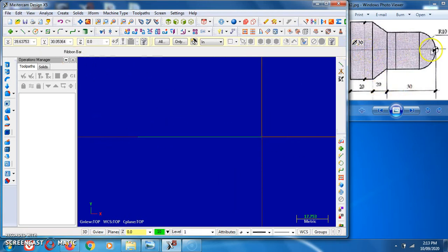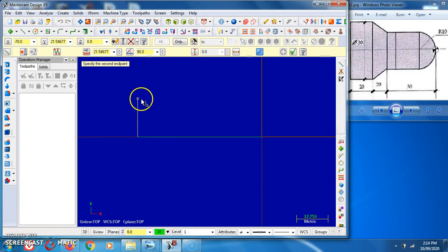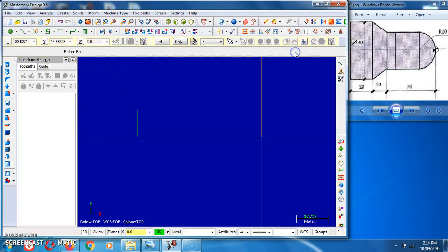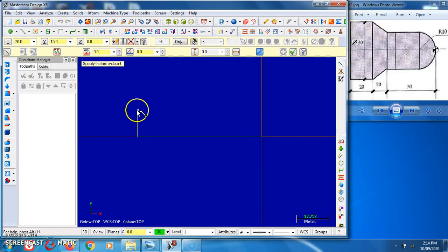Now, as we develop the half portion of this given figure, from this half distance there is 15 mm from the left hand side. So click on the line and make the distance of 15 mm, with the angle of 90 degrees, press enter. Then prepare another line of 20 mm. Click the endpoint as center, prepare this line as 20 mm, and the angle required for the movement in the rightward direction is 0 degrees. So put the 0 angle, press enter.